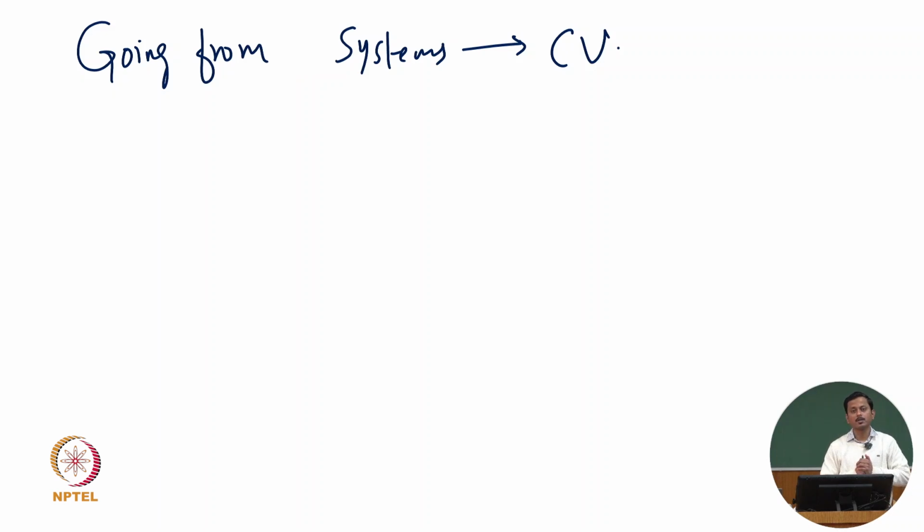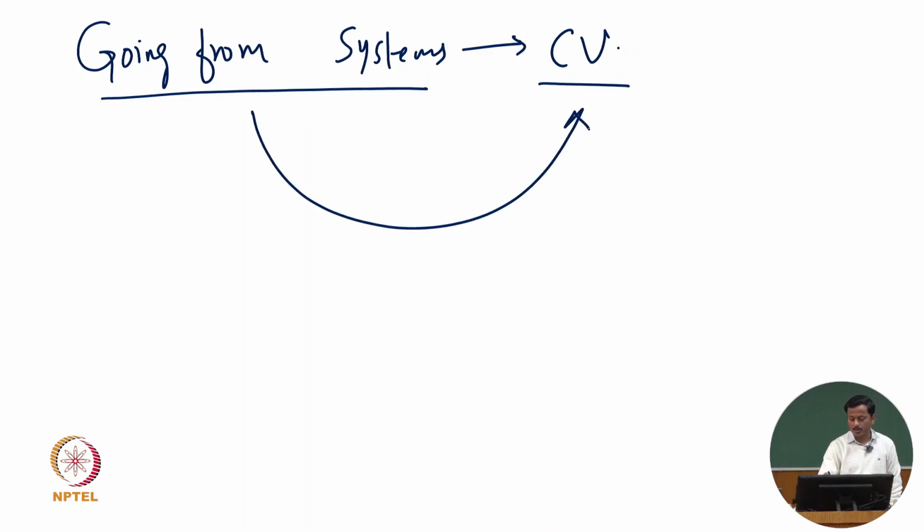But Newtonian laws, the conservation laws, were developed for systems. So these hold exactly for systems. So for example, the first law of thermodynamics, Newton's second law. However, because it is very difficult for us to keep track of deformable systems like fluids, I mean water or gases, liquids or gases, we employ a control volume approach. So to apply the conservation laws, we need to go from a systems approach to control volume approach, and we need a mathematical transformation.